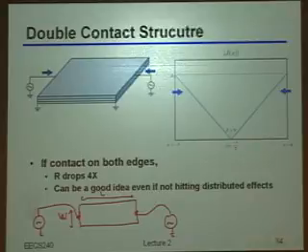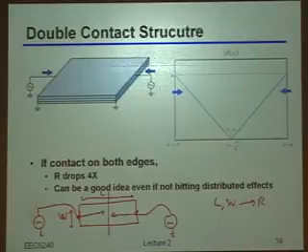what's the worst resistance that either one of those sources would actually see, individually? What's the worst case resistance you can think of? And let's say, by the way, that originally with the L and W, you had a resistance of R. So, yeah, it's half of that, right? Because this source has to go from there, and this source has to go from there. If I draw a line in the middle, each one of them has half of the original resistance. Okay? So now that got me one factor of 2. Where's the other factor of 2 coming from?